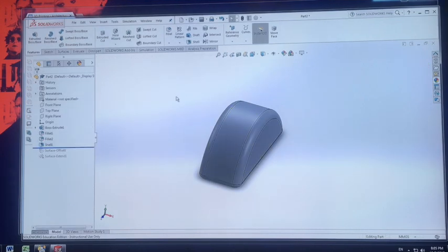Now if you've done that for your object already and you've measured your object and it's a 1.5mm thickness or 1mm or something like that, and you're 3D printing and the 3D printers or their website suggests a minimum of 3mm, then you need to change your object.